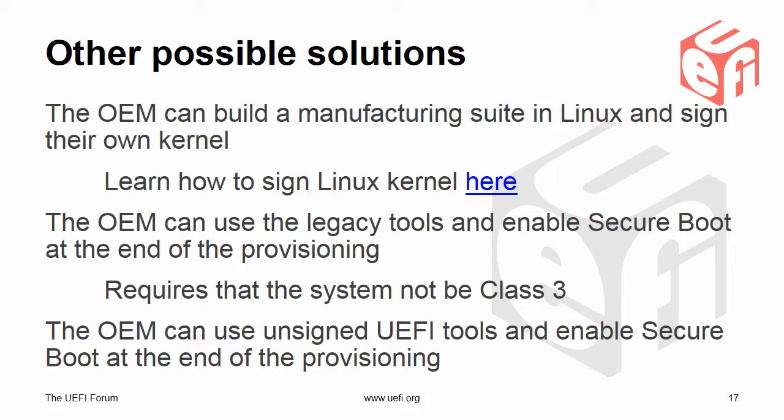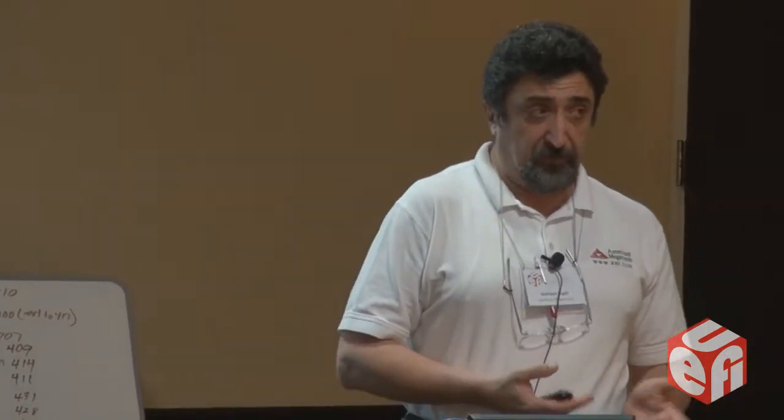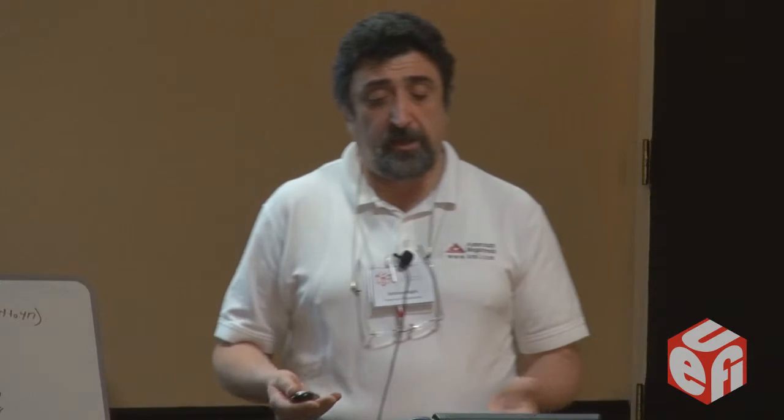Other solutions are obviously related to not enabling secure boot in manufacturing, keeping your platform with secure boot disabled in manufacturing, but ensuring that you enable it before the unit leaves the manufacturing line. Also in this case there are really two cases, because as we were indicating before, if you use legacy tools you cannot use them on class 3 systems, but if you have unsigned UEFI tools, you can use them on any system, class 3 included.